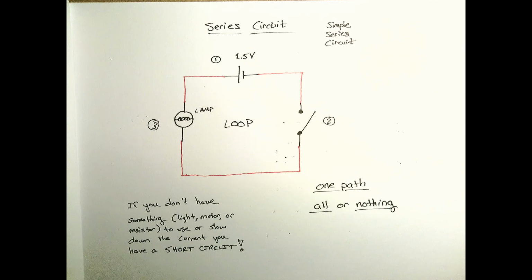Okay? So those circuit breakers in your basement or closet or garage or wherever your breaker box is, they're designed to let a specific amount of current go through, and that current is tied to the size of the wire that's in your walls. Okay? So the whole system is deemed safe when they build the house. And then your breakers are there to make sure that you don't exceed the safe limit of electricity passing through those wires. Otherwise, bad news bears.